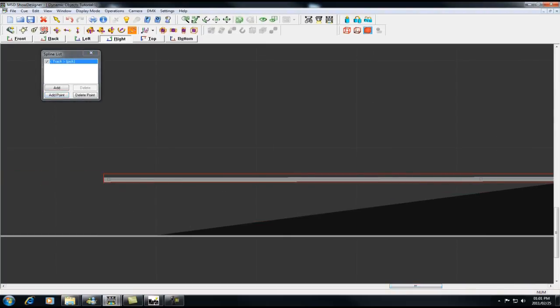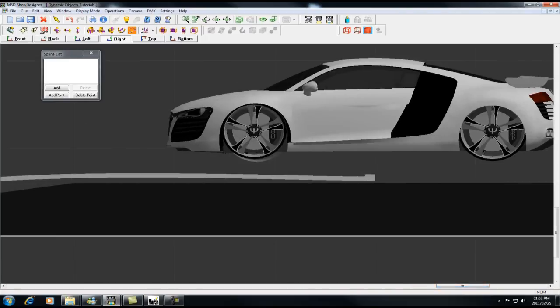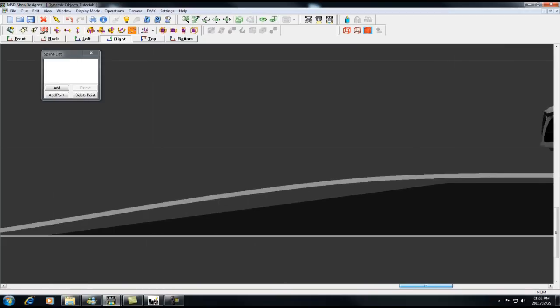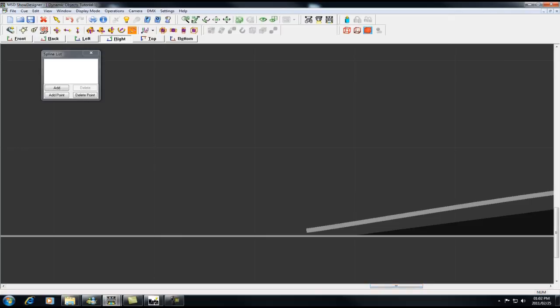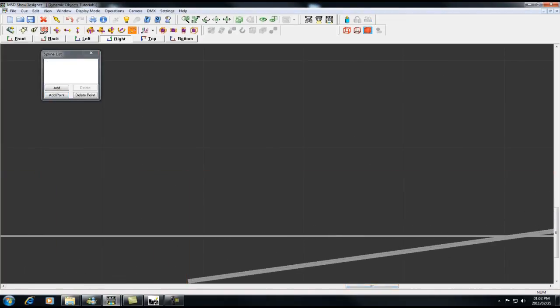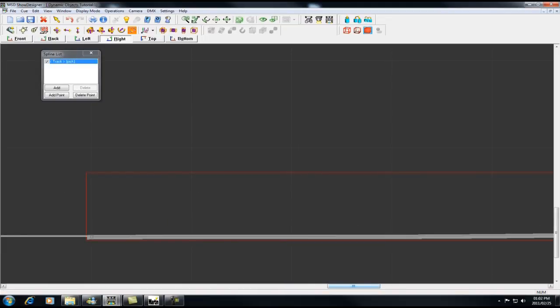When it adds in a point, it'll copy the distance from the previous point. I then stretch it to about there. You will now see it bows the track slightly, which gives the motion a bit more of a smoother feel. You can, however, change that by adding in more points on the spline list. Once you've got that, click on the track again, add in a point, and then manipulate it to where you want it to go. In this case, I want the car to stop here.